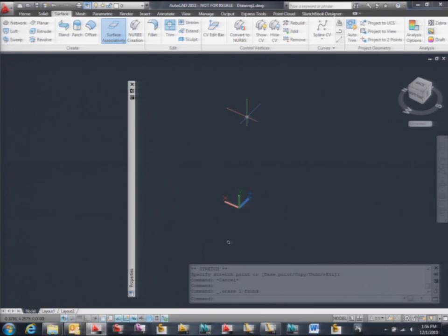So what happens with sketch? When you're doing the sketch, AutoCAD is recording every point where you're going through, and then it creates a set of tiny little lines from each point to the other, right? Well, maybe that could be useful sometimes, but now, check it out.